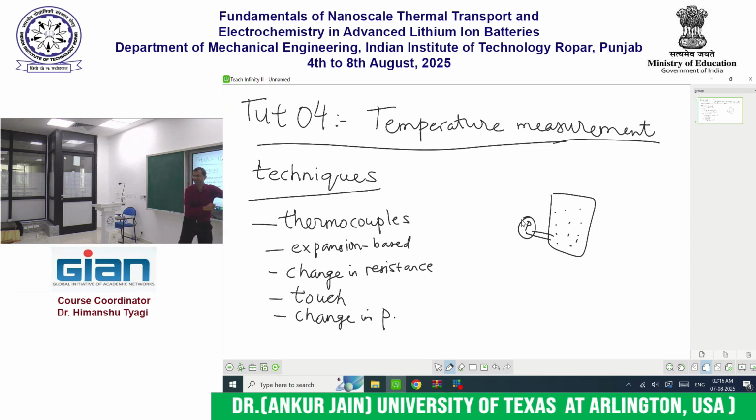As I take it here and there, if the pressure in this cylinder changes, then I will know that the temperature has changed. Provided two things, the volume is the same and it is an ideal gas. Because for an ideal gas, we know PV equals nRT, volume is the same, the mass is the same, pressure is in fact proportional to temperature. Right? I can easily see how the temperature changes because of changes in pressure. What else? Maybe one more item? Optical, yes. So changes in optical behavior.